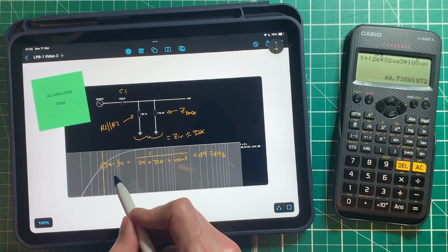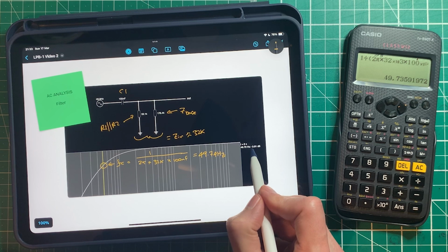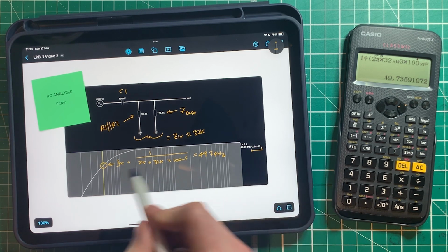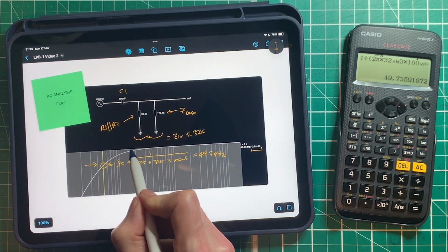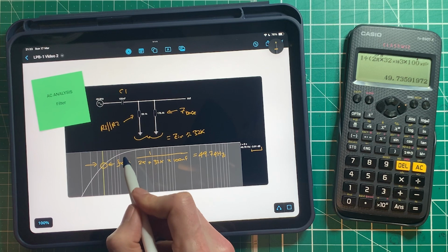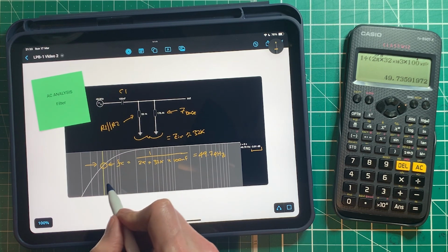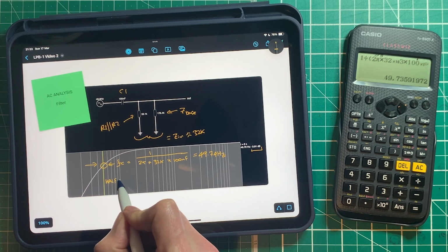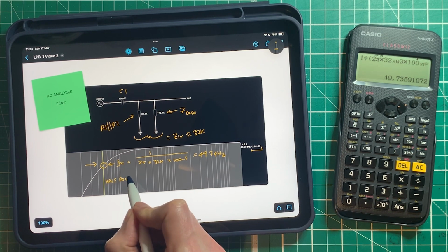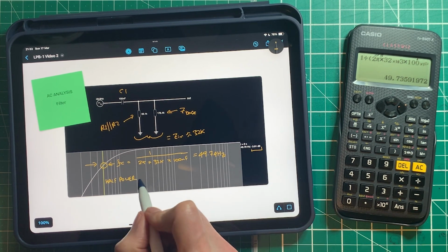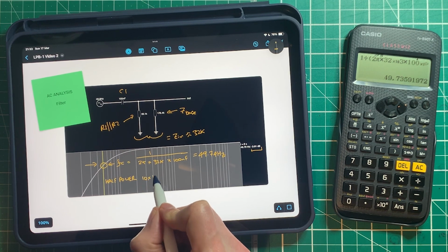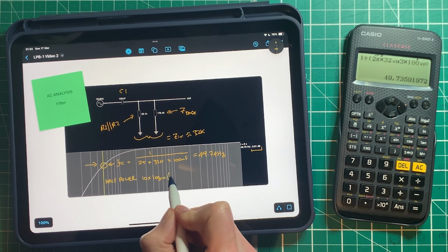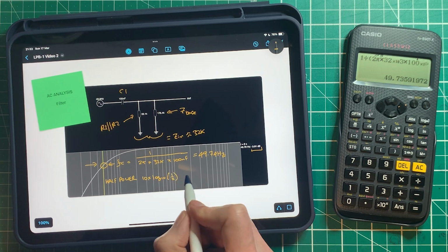Now, you might notice that it's taken at minus 3.01 decibels and it's down here, not up here. And there's a reason for that. It's because it's taken at half the power. Half power. And I'll show you why it's minus 3. So the power equation is 10 times, because it's power, log base 10, and it's half, because it's half the power.